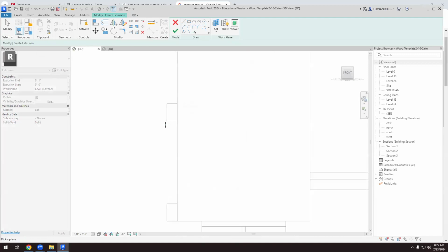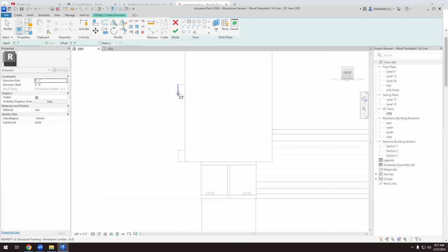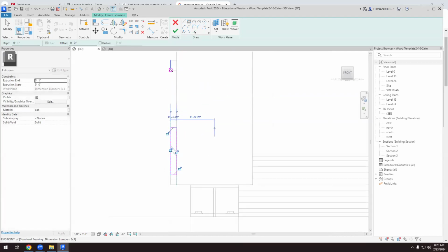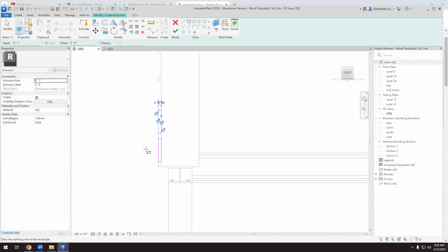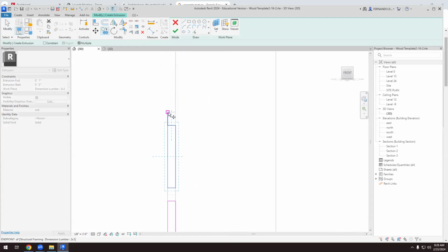And we can select this, not the line, but the rectangle itself. Okay, so we are working on that plane where this rafter starts. So select this one. And now I can create a rectangle here. And if the distance of all these elements is the same, I created the array, so the distance should be the same. I can copy.